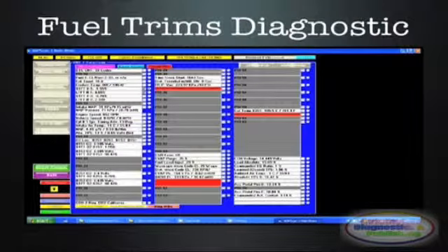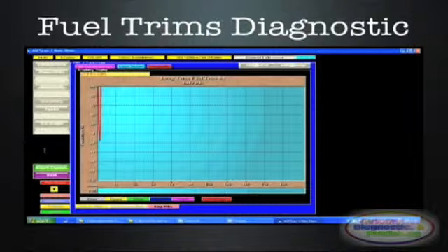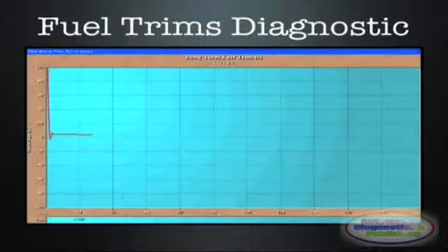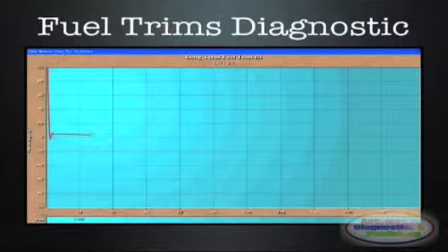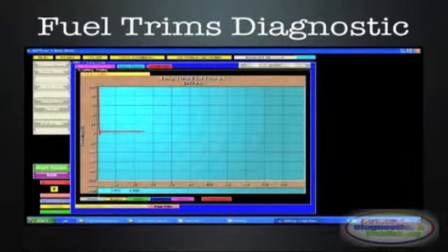The short-term fuel trim will always try to stay at 0. If it goes plus or minus, it will affect the long-term, and then go back to 0. Again, you need as much screen detail as possible. The speed of the scan tool is also important. The long-term is very slow, meaning that this PID reacts to the more persistent air-fuel imbalance.